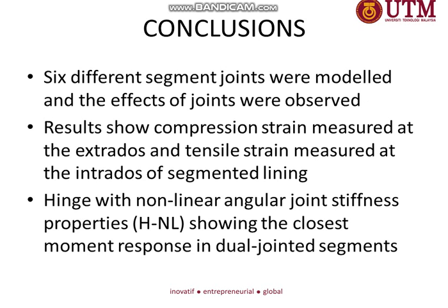In this presentation, I have embedded a few different segment joints, and different joints show different patterns of results. In general, the results show compression strain measured at the extrados and tensile strain measured at the intrados of the segment tunnel lining, and the distortion occurred highly at the crown.